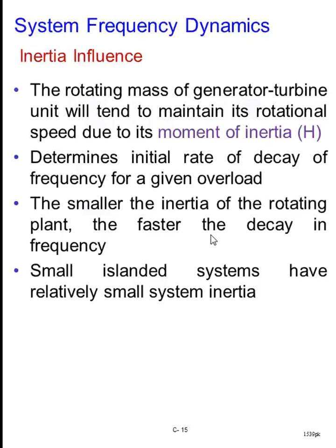Thus, for the same amount of load change in an isolated system, the decay of the frequency will be sharper and faster. However, for an interconnected system, since the inertia is comparatively more, the decay in the frequency will be slower.